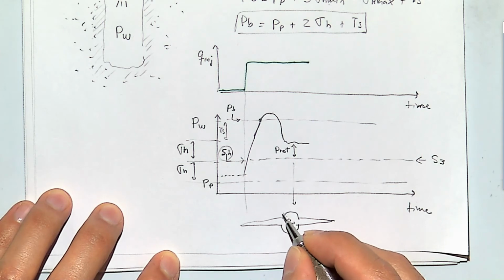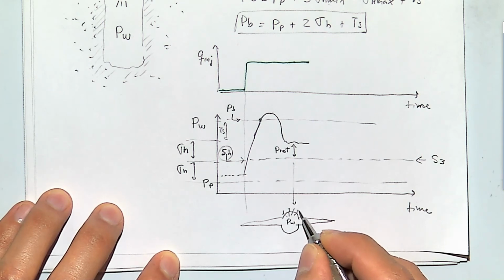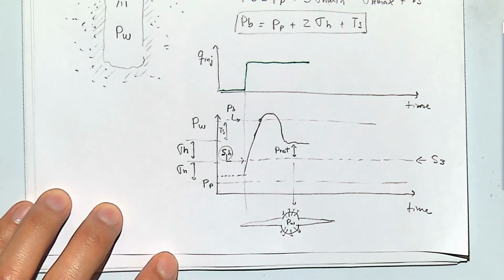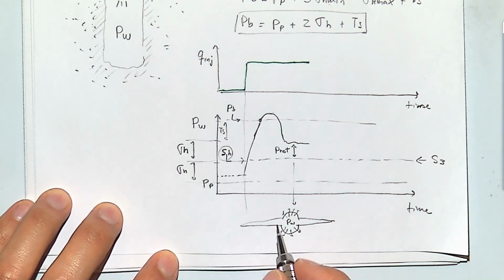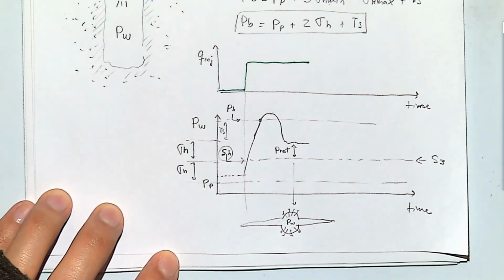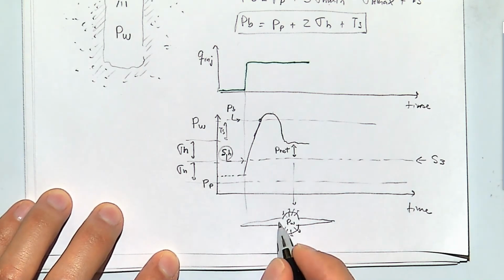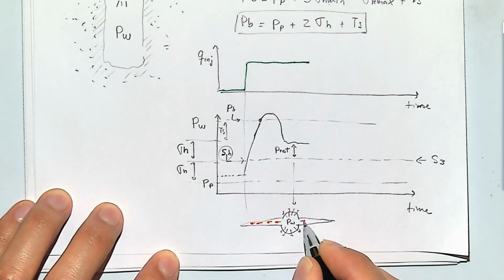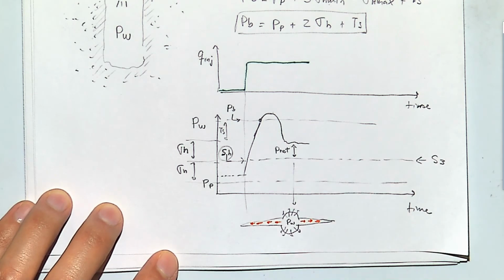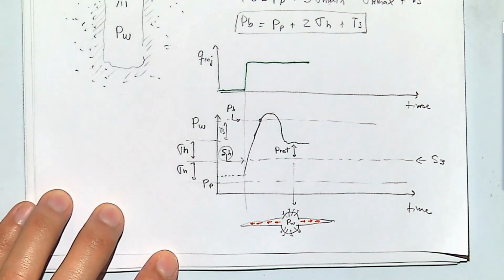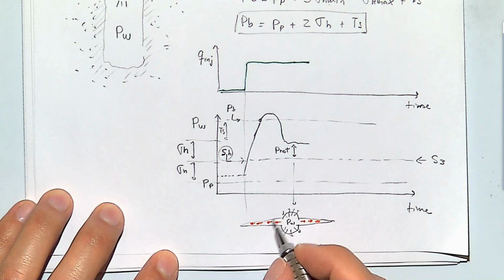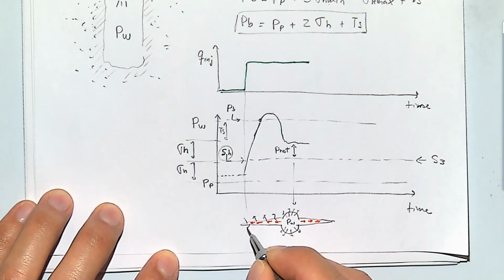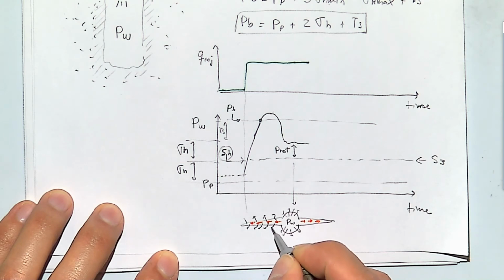So some of the drilling mud is filtrating through the rock around the wellbore itself, but also I have fluid, in this case drilling mud, that is going into the fracture, is helping the fracture to open up and propagate more, and some of that drilling mud is filtrating also into the rock, but out of the fracture.